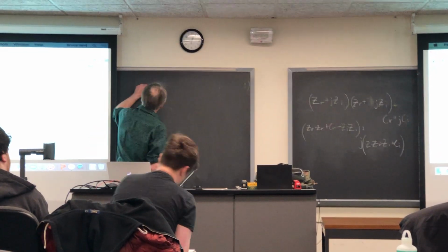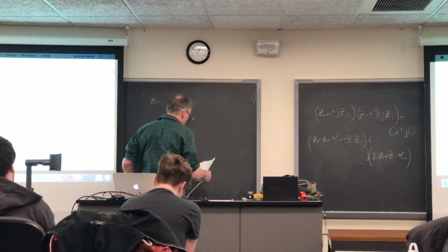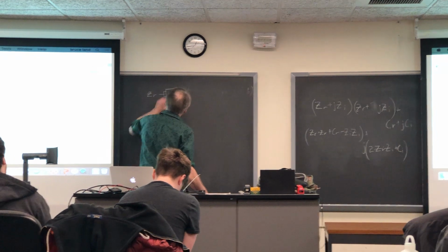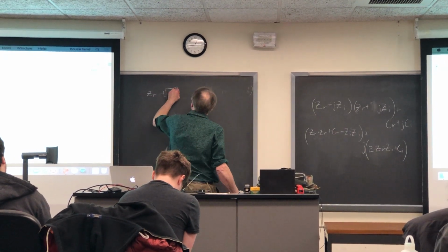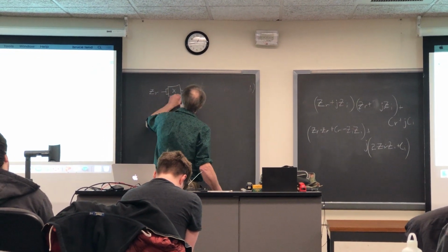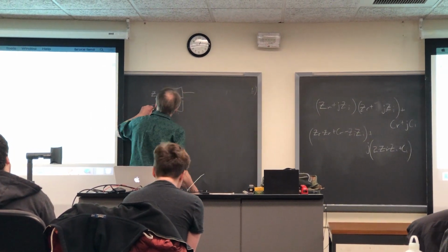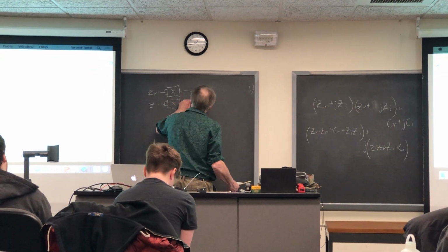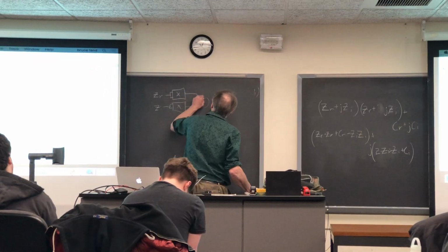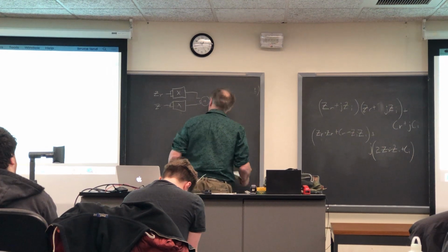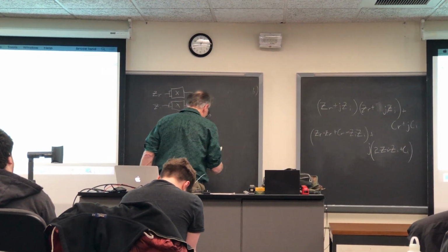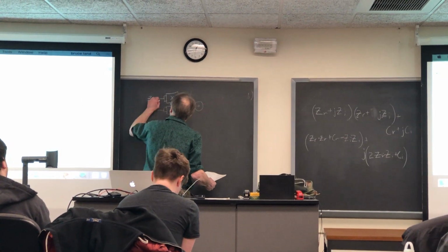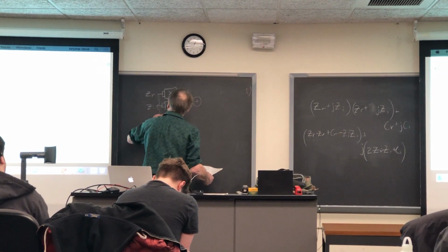You can imagine feeding in a ZR into a multiply module, which you instantiate, feed it in twice, bring it out, another multiply module, feed in ZI twice into that, bring this out, add them together, along with a third multiply, which takes one input from each.